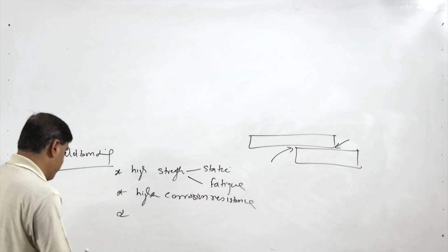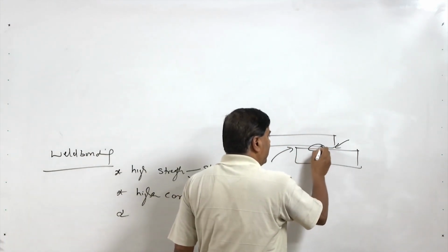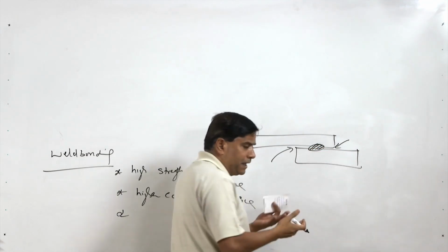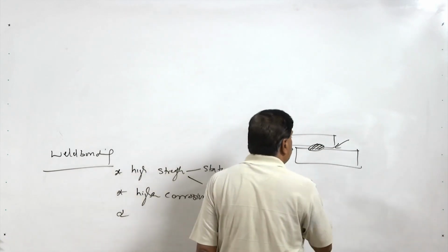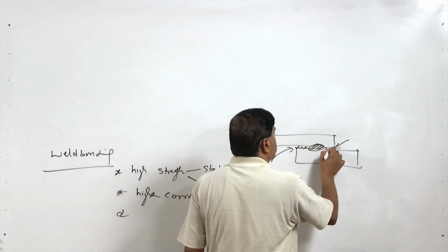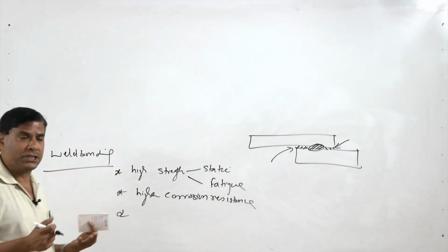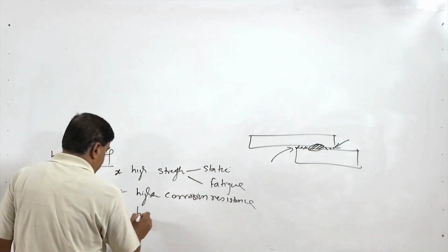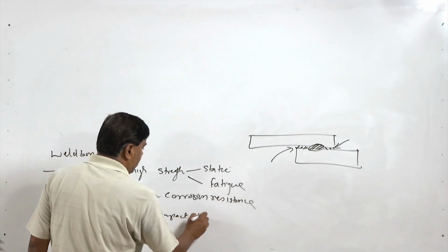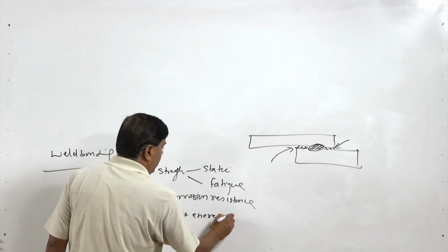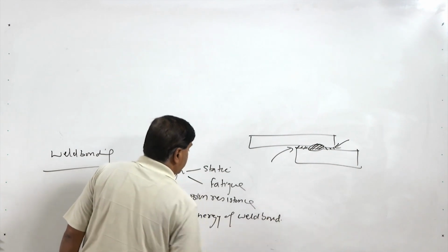At the same time, the combination of the metallic connection and the increased distribution of the stresses over a larger area of the adhesive joint basically increases the energy required under impact conditions. So, the weld bonds have high impact energy as compared to the spot welds.